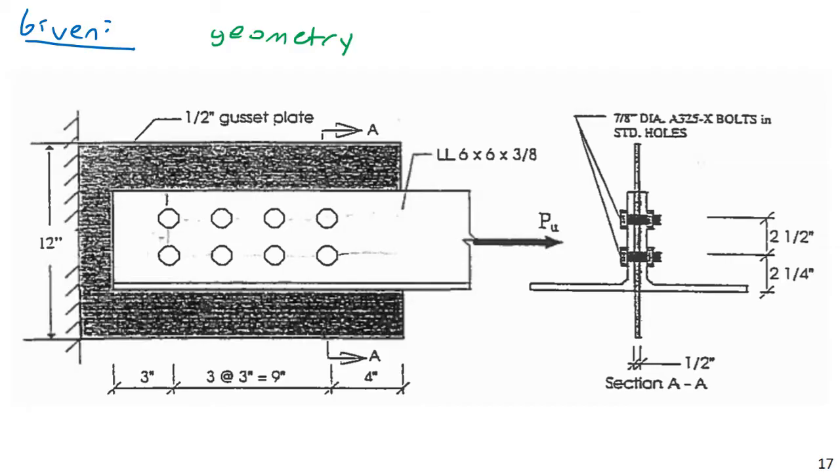Then, I do want to list a few things. A lot of the things we do in terms of our tension members, again, tension members are our long, slender elements. In a frame structure, they're the things you see the most. In this case, our angle irons, our L shapes, are our 6 by 6 by 3/8. If you ever see something labeled as just L 6 by 6 by 3/8, that would refer to just a single angle iron. An LL refers to 2 angle irons joined together back to back.